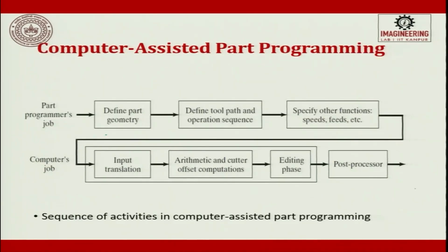So, this is the part programmer's job: define part, define tool path operation, specify other functions, speed, feed, etc. The computer's job will be input translation, arithmetic and cutter offset compensation, editing phase, and then it does the post processing.